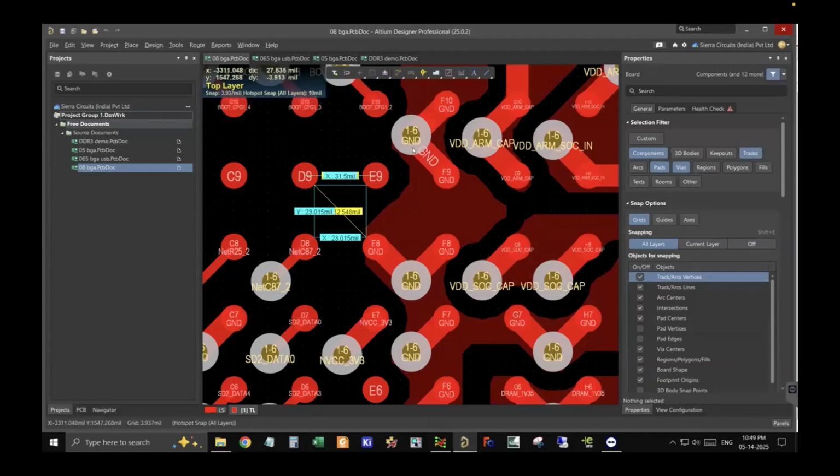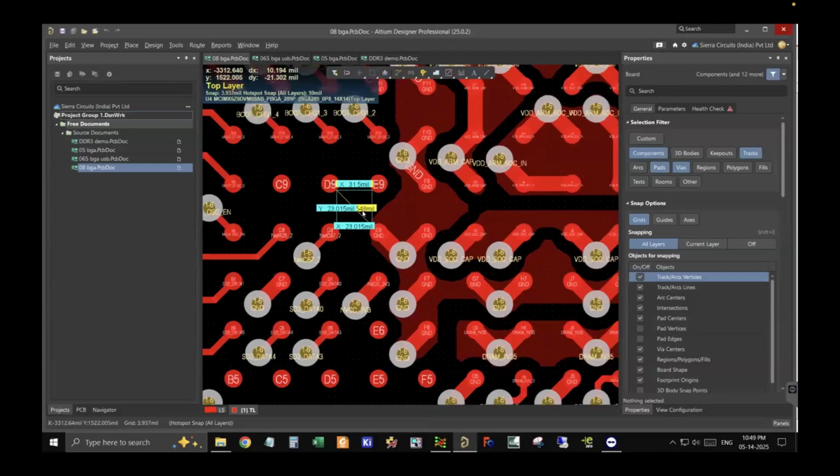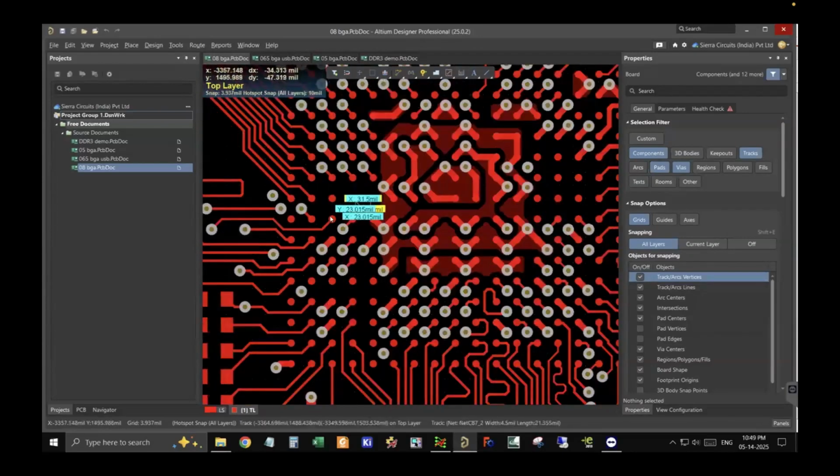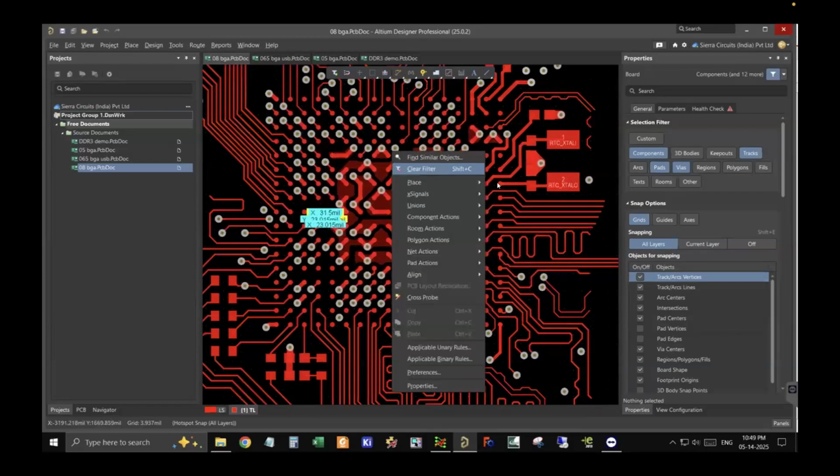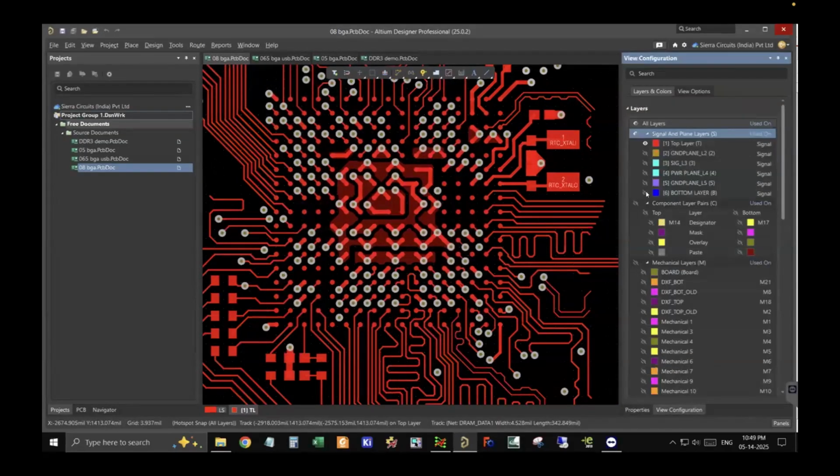But if that is not the case, then easily you can use a normal through wire in 0.8 pitch BGA. So here, half ounce on the external layers, copper foil should work perfectly fine. The next thing after placing all the wires is to place the capacitors on the bottom layer.